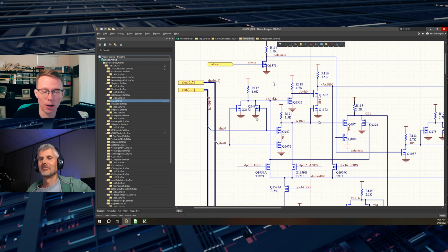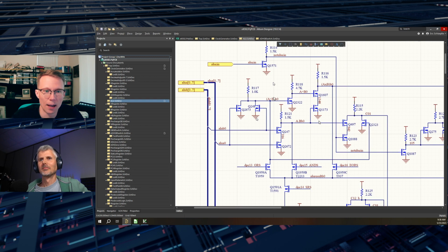I did a lot of work in part selection to try and find the lowest gate capacitance I possibly could. And it's low for a power FET, but it's still much higher than a typical transistor that you would find on an NMOS device like this. Yeah. Why did you go for power FETs rather than something smaller? I mean, it really was just the DigiKey selection. So I just pull up DigiKey, look through the selection chart, and then I optimized it for the lowest threshold voltage I could find along with the lowest capacitance.